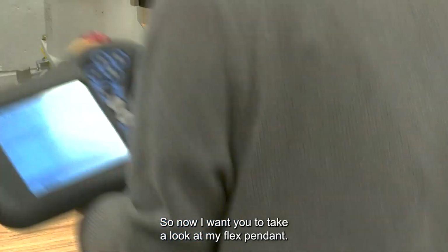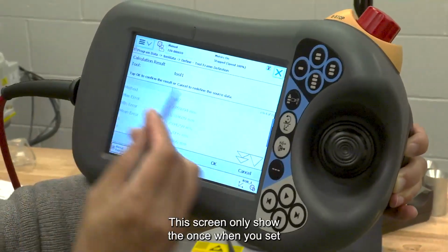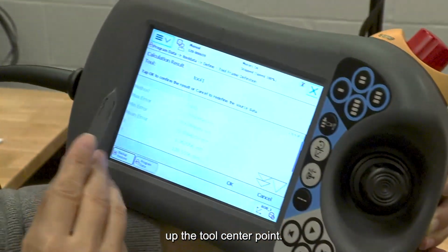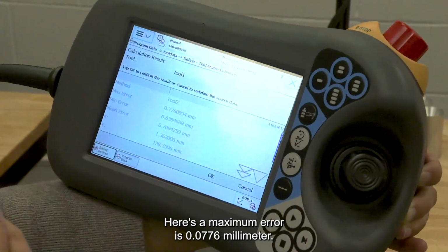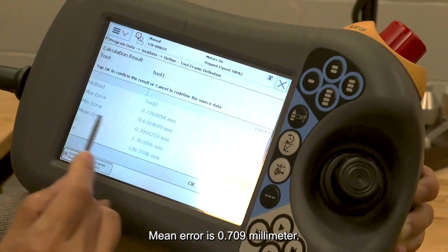So now I want you to take a look at my flex pendant. This screen only shows once, when you set up the tool center point. Here the maximum error is 0.776 millimeter. The minimum error is 0.638 millimeter. Mean error is 0.709 millimeter.